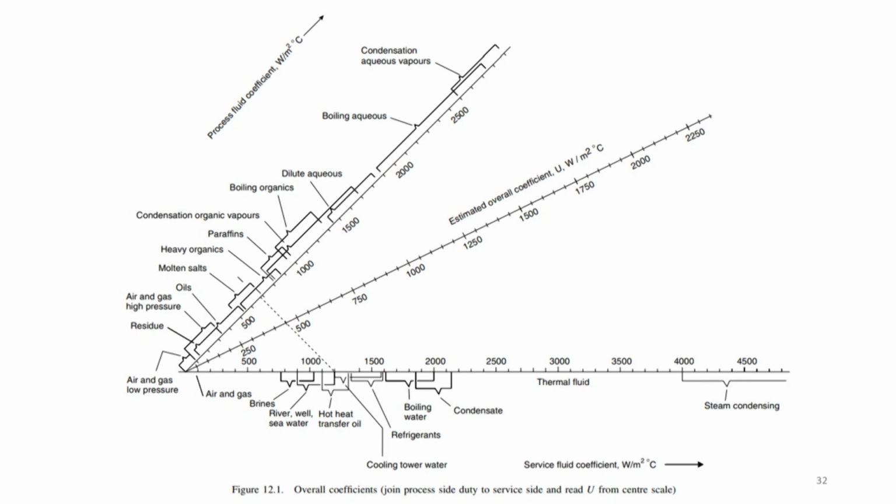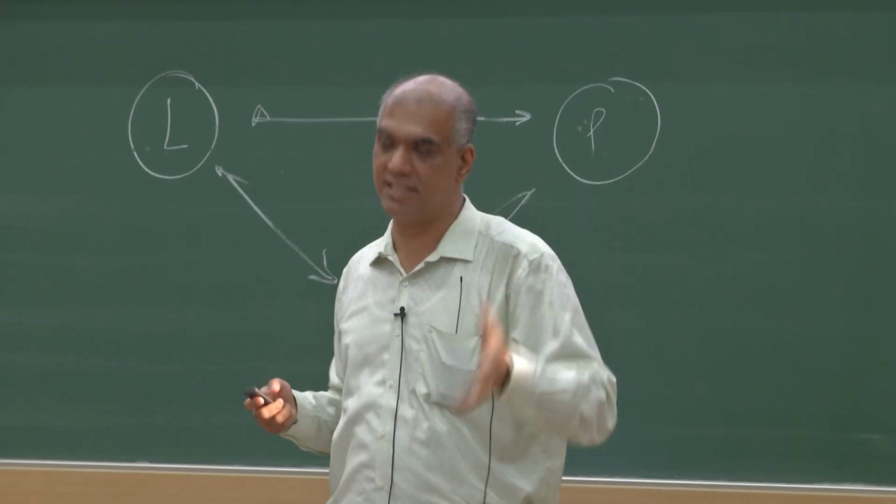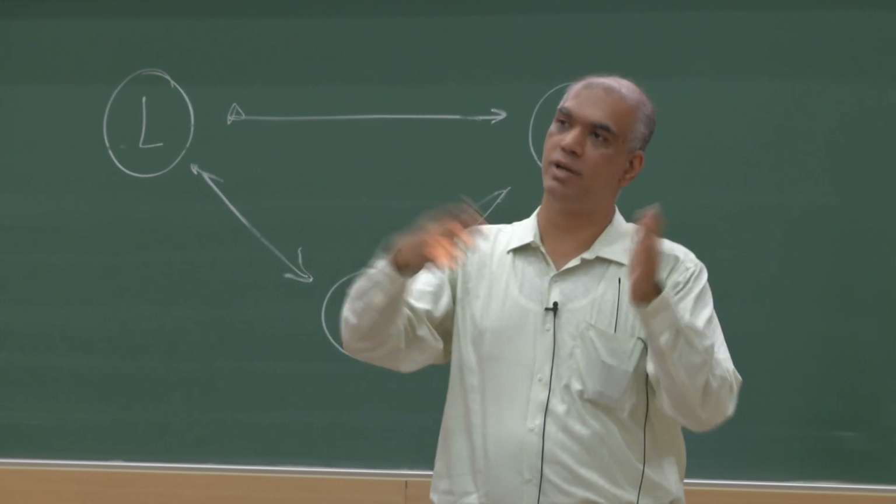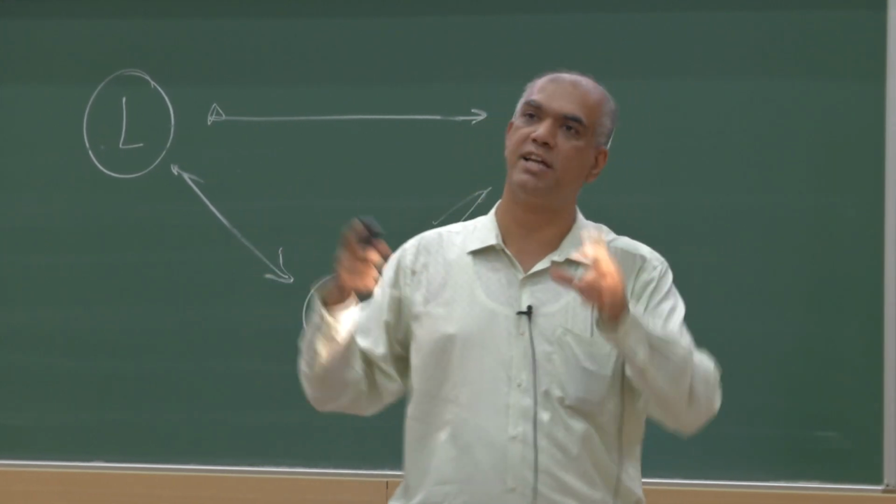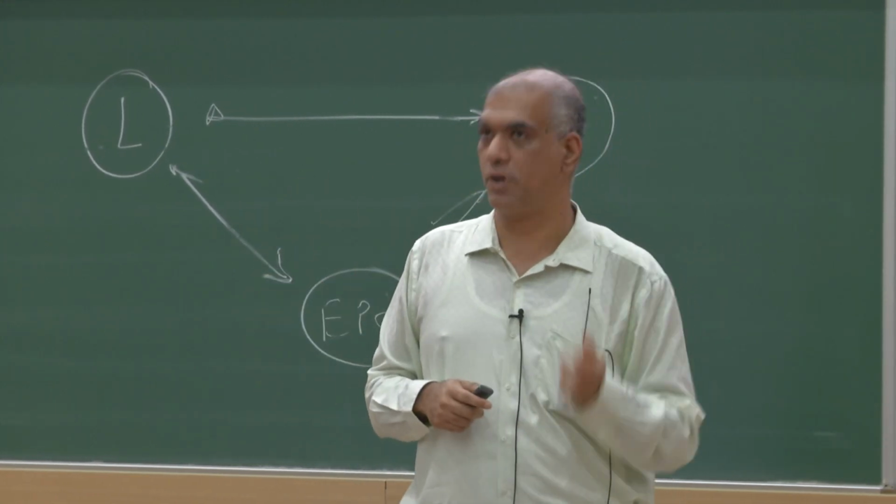Now I go to nomograms. This is again from Coulson, Richardson. So one thing is figuring out what is the heat transfer coefficient. Now there are multiple ways. What I want to highlight is sometimes there are multiple ways to check things. One way is to, in DWSIM or Aspen, put in a heat exchanger and you will calculate the output streams and you will calculate what is your heat transfer coefficient.